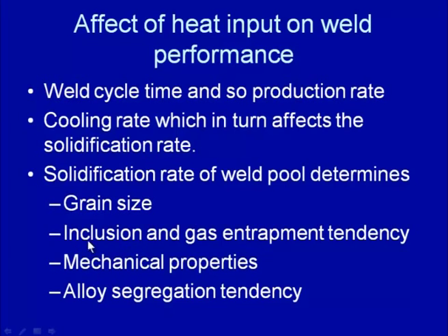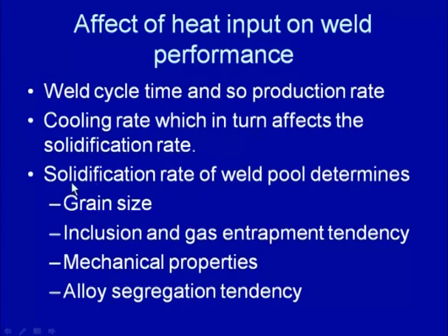Therefore, if any inclusion is present or gases in the dissolved state are present in the molten weld metal, they will not be able to come up to the surface of the weld pool, and that is why they will show a greater tendency for entrapment in the weld pool. So, lower heat input, higher cooling rate, and higher solidification rate will increase the inclusion and gas entrapment tendency.